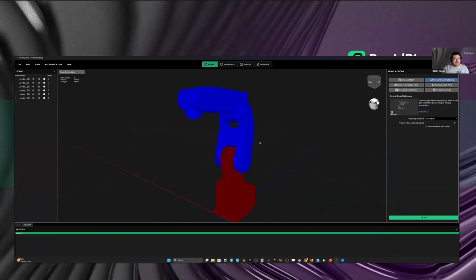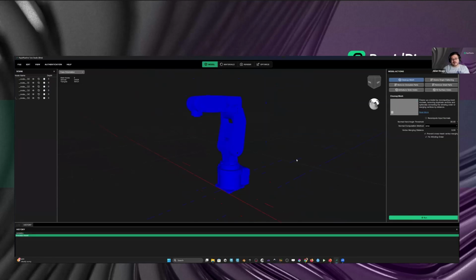But if we go back to the face orientation, we see that now a whole part of the model is flipped. And that is not a problem at all. We can go into our mesh cleanup operation and disable the recomputation of normals. We don't want that happening here at the moment. We just want the winding order fixed, right? If I run it now, and this was pretty fast, we have it corrected. But what it actually does is multiple things at once.